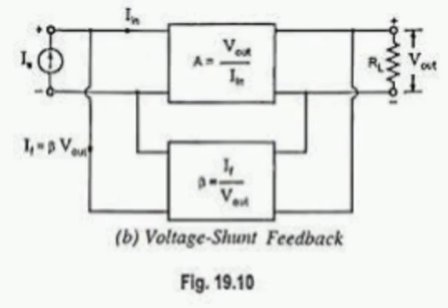For emitter follower amplifier, effective AC load resistance small re equal to capital RE parallel with RL. AC saturation current IC sat equal to ICQ plus numerator part VCEQ by re. VCEQ by re is separate. AC cutoff voltage VCE cutoff equal to VCEQ plus ICQ re. AC output compliance of an emitter follower PP equal to minimum of 2 ICQ re, 2 VCEQ.